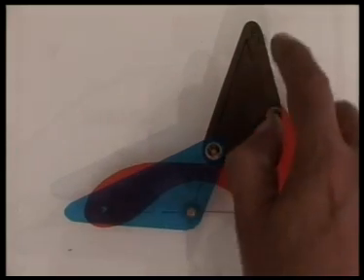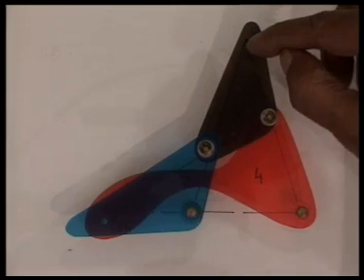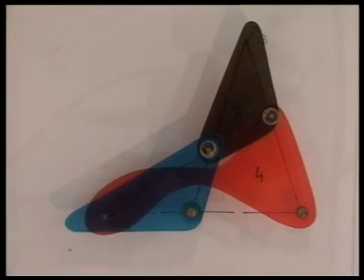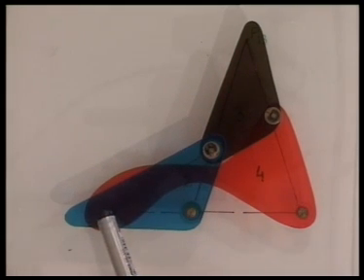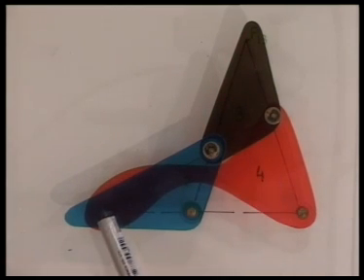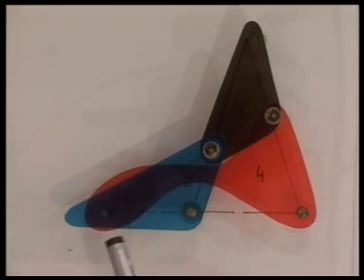You see all other points in this link 3 is moving around this configuration. This point has 0 velocity, is hardly moving. Now, to see the significance of 2, 4, let me consider this point, a coincident point on link 2 and link 4. That means one point on link 2 and exactly just below this point, a point on link 4. These 2 points on link 2 and link 4 at this instant have same velocity. That is why we call it 2, 4.